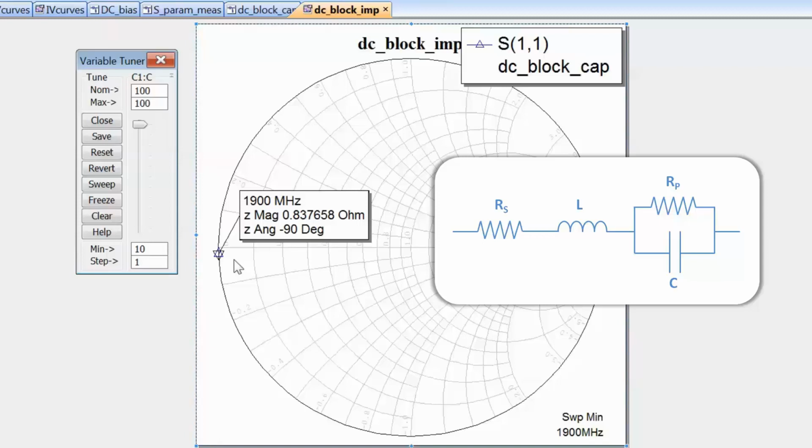And hence we end up having a series LC resonator. You can actually find an element with a capacitance value associated with the parasitic inductance value which makes it resonate at the frequency at which you're working, and then at that frequency your impedance will be exactly 0.